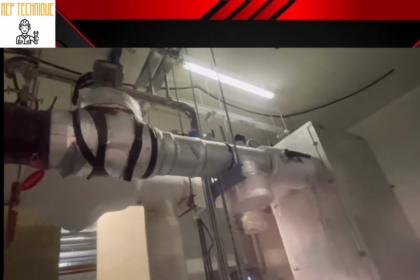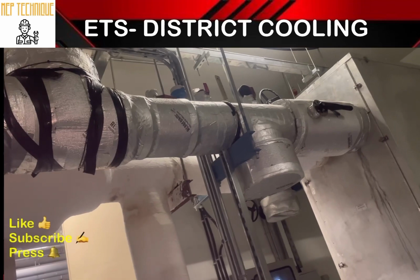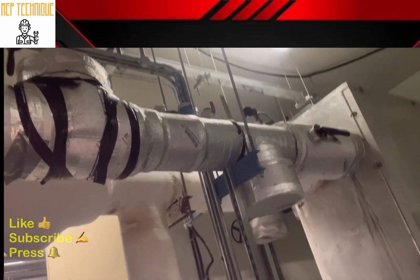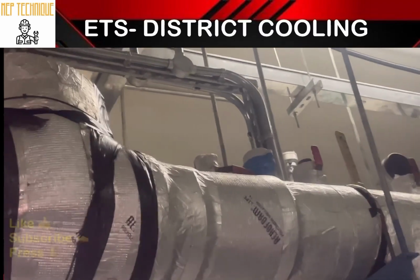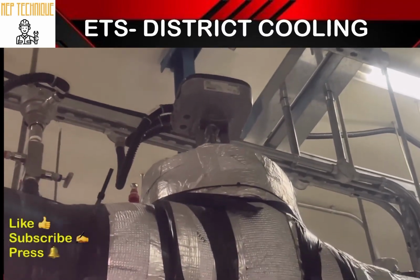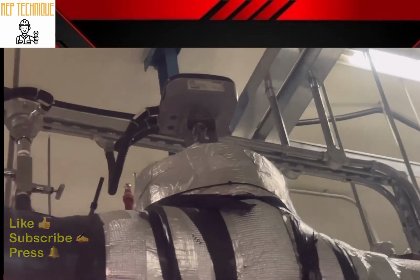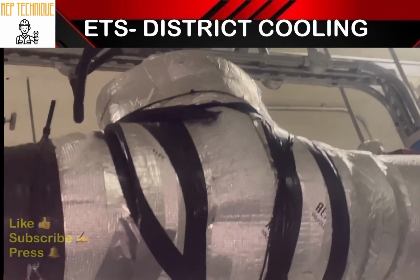In the chilled water secondary, there is also a temperature gauge and pressure gauge, and there is also a TIT, the blue one you can see. This is the TIT, temperature indicator transmitter. There is also an actuator valve which is configured with a PICV.